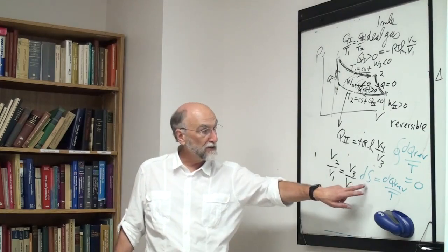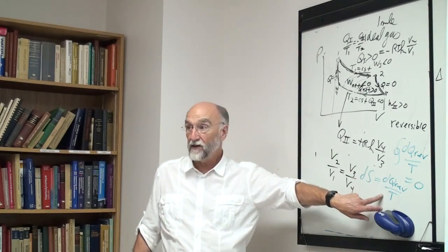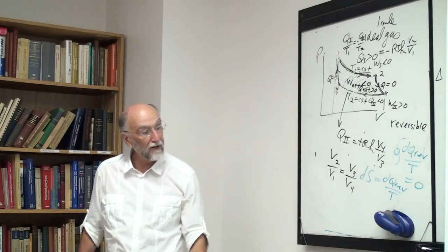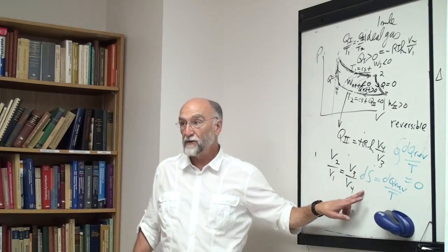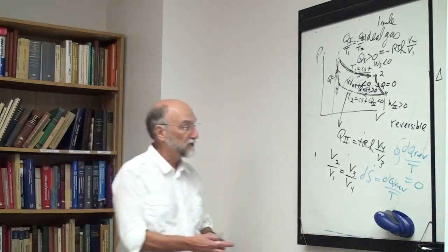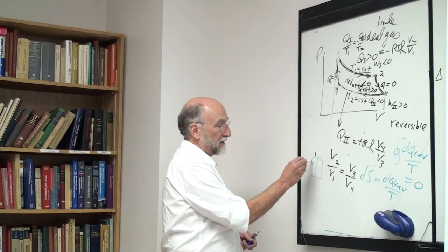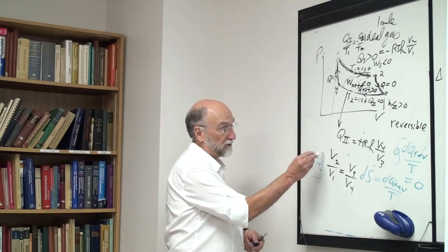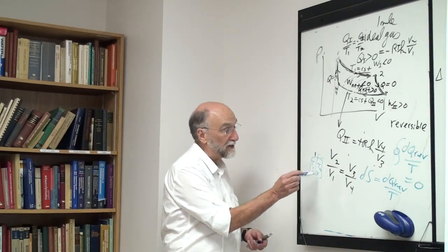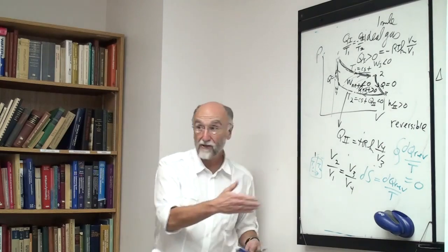Then they also observed that that's only the first half of the second law, that there is a property called entropy where dS is dq reversible over T. It is a state property, which is the reason I went through here. Then the dS total must be greater than 0. It was again based on two things. I showed this where I had two systems in equilibrium at T1 and T2, and you could show that heat flows from high to low temperature, the delta S total was positive.